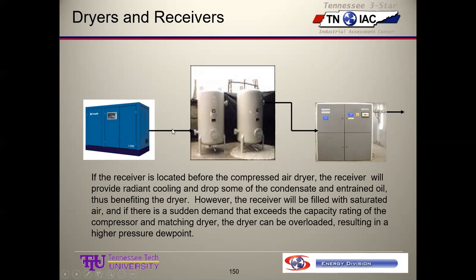Some of the moisture will condense before it gets to the dryer, and some compressor lubricant could fall out if this is a lube injected compressor. So any moisture and compressor lubricant that I can trap out of these tanks just makes the job of the dryer that much easier, because if these tanks weren't here, there wouldn't be time to cool this down and condense anything. That air would just run straight to the dryer, and the dryer would see the full moisture load. So this takes out a little bit of moisture and potentially some lubricant, which helps the dryer.